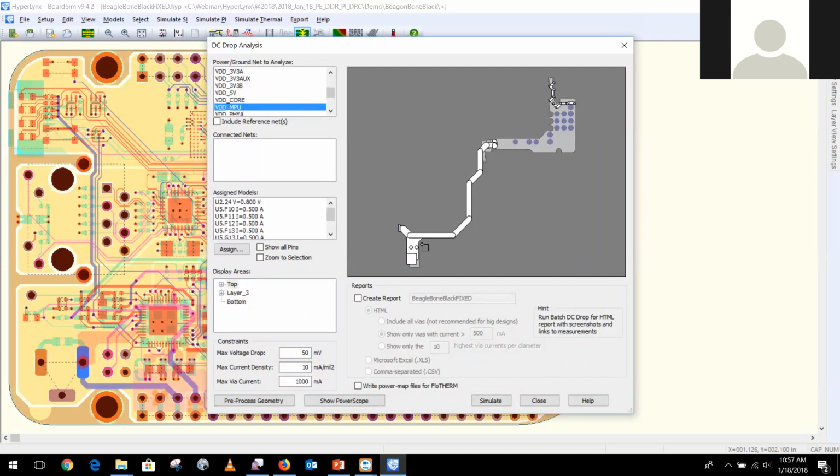Now, before you do any simulation, you need to look at this and see if it makes sense, right? If the source is on the lower left and the upper right is the destination, and I'm generating a voltage from the lower left to drive to the upper right, you don't want to have narrow traces like this. That's a resistor. You want bigger planes on this side to minimize voltage drop. So in this design, they didn't do it properly from a topology standpoint. They're sneaking in with a little trace and then expanding it out. Well, guess what? By the time the voltage gets to here, through whatever current amount it takes, the voltage has already dropped. And now having a big plane will distribute that lower voltage to the chip, which is not as good as having the bigger plane on the left and a smaller trace on the right. Okay, anyway, so that's looking at it.